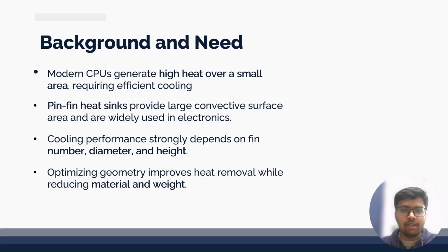Before diving into why we are using pin fins, we have to see why pin fins work so well. Pin fins offer very large surface area in a compact volume, and a multi-directional airflow path enhances heat transfer even at moderate air velocities. But their effectiveness strongly depends on the geometric choices. With too few fins, cooling is very weak, and with too many fins, the air cannot pass through, choking the system. So optimization of these parameters is essential. Optimizing geometry improves heat removal while reducing material and weight.